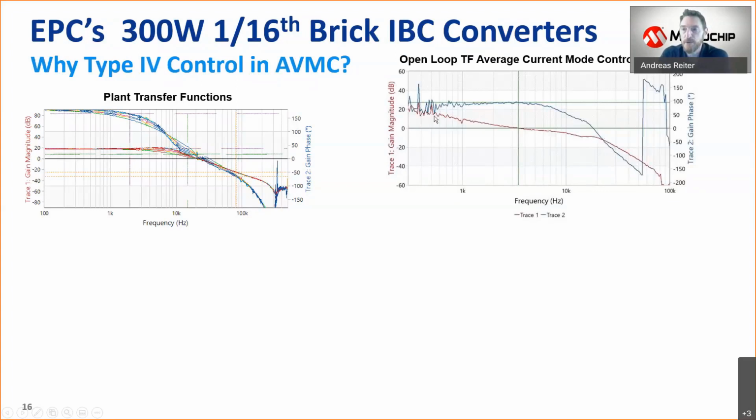If it were a single phase converter, the gain would just drop steadily and would give us a better gain margin here at higher frequencies. But with this second bump, unfortunately, we get this flat gain region, which, if we are trying to push the gain too much, will come closer and closer to 0 dB. And this is then opening a high frequency noise gate into the control system, and the control system will start to reproduce this. We'll see the effects of this later, also on the design.